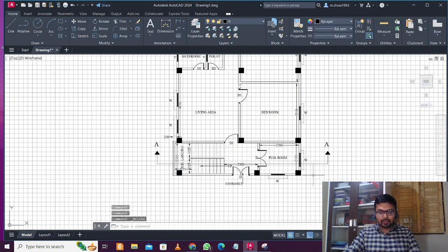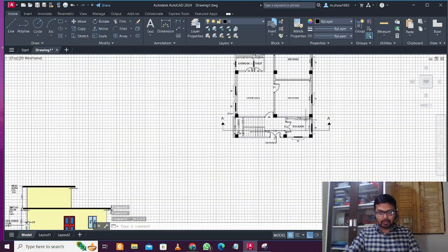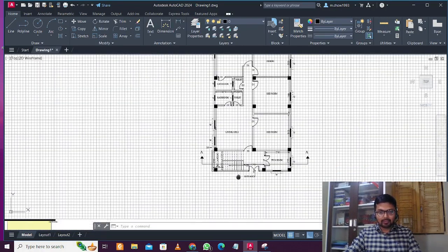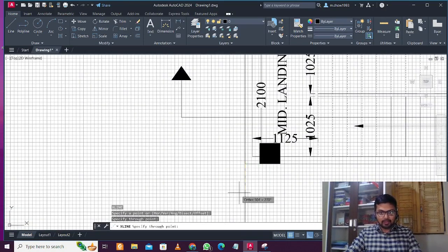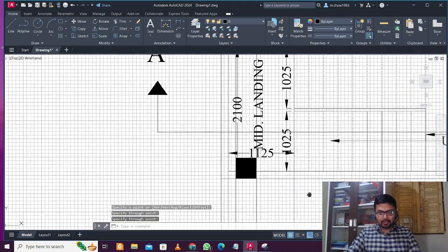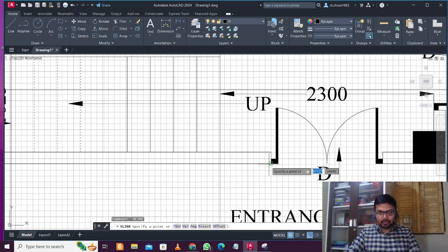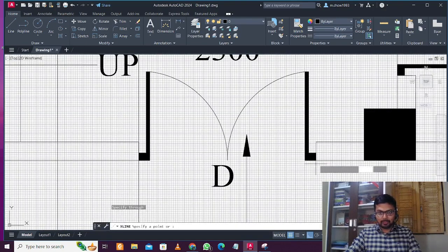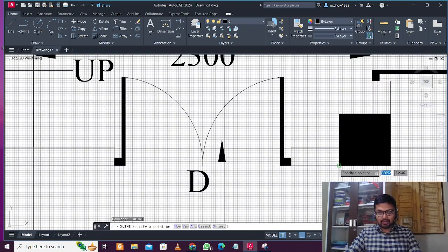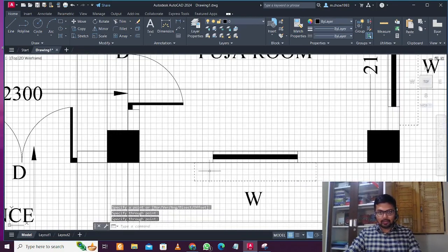Okay, this is the section AA which we'll prepare. So for preparing section AA, I'll enter, and now we'll need everything in detail, right? So take every single thing in utmost detail. Here the staircase starts, where the staircase ends, everything should be taken. Will require this time in detail. So that's the beauty of a section. Many engineering and architectural things can be found out when you see a building section.